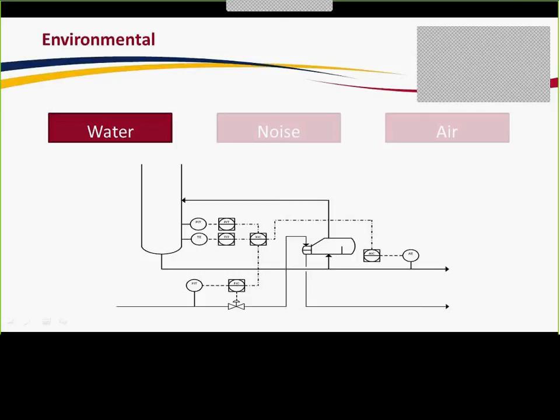And if the concentration of methanol and DME is too high, the flow rate of steam entering the reboiler will increase, therefore decreasing the amount of methanol and DME in the stream. So in this way, the concentration of methanol and DME that's leaving the water column is not a huge environmental factor that needs to be considered.